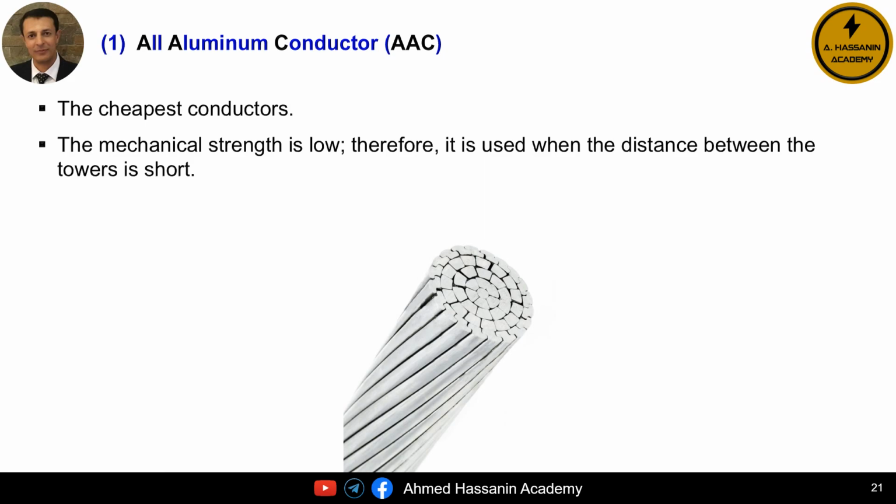Due to this low mechanical strength, this type of conductor is suitable only when the distance between transmission towers is short, because large distances mean a greater tensile force and weight stress acting downward on the conductor. Therefore, such applications require high mechanical strength, as we explained earlier.